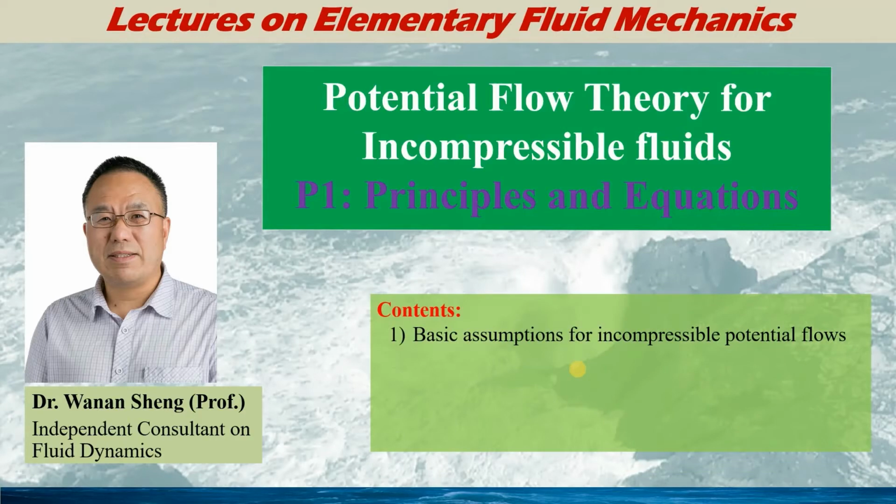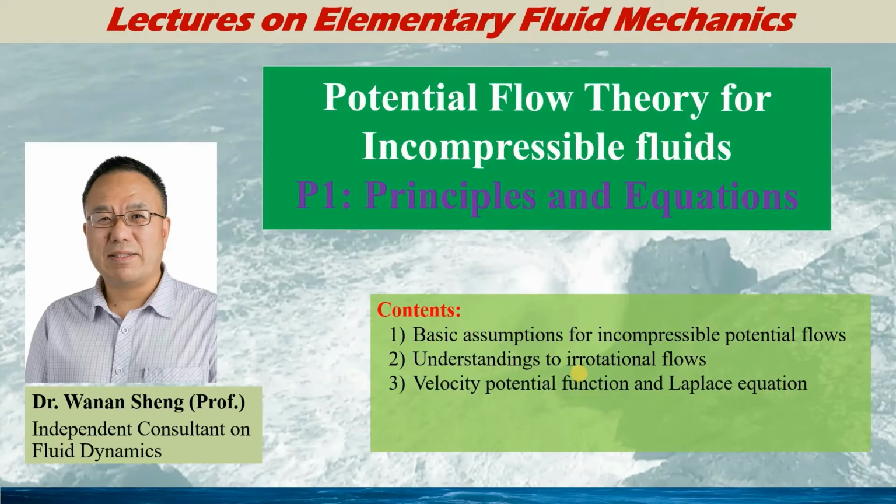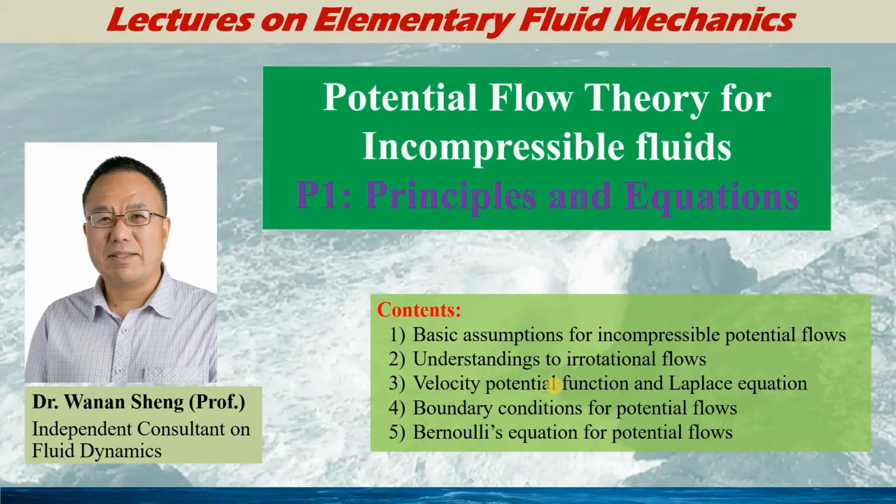In this talk, I will first introduce the basic assumptions for incompressible potential flows, then make introductions to the understanding of irrotational flows. And then I move to the velocity potential function and the corresponding Laplace equation. Then the boundary conditions for potential flows, and the Bernoulli's equation for incompressible potential flows.